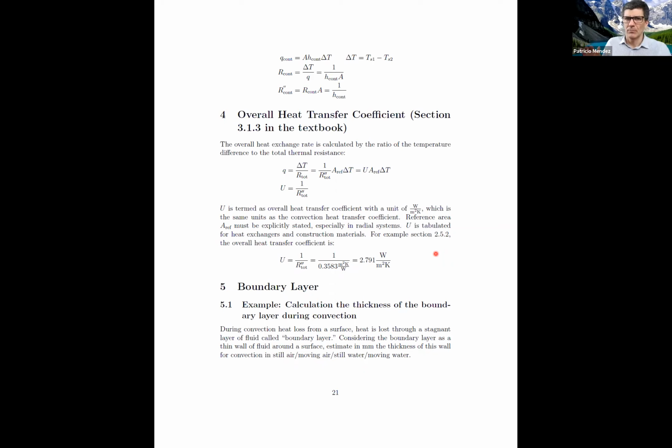To give you an idea, I am here in front of the camera, and my hand is more or less 33 degrees. The skin of my hand is at 33 degrees. The air is more or less 20 degrees. So there are some currents of air going up because of the warm air coming from my hand. This motion of air is creating a boundary layer. And the heat losses from my hand into this air, we call it convection, but in reality is conduction through this boundary layer.